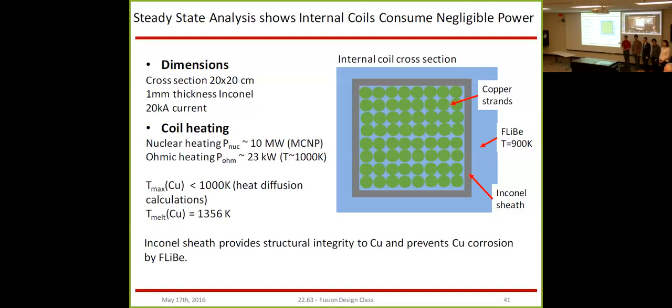What temperature were you assuming the superconducting diverter coils were running at, and what current density? I believe it was 30 Kelvin. And I don't remember the critical current density off the top of my head, but those were calculated based on the poloidal and toroidal magnetic field contributions and the critical current density in the most recent YBCO tape that has been produced.